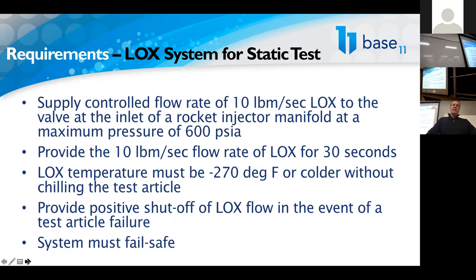And I think this would be true in all cases, whether it's a rocket or a static test, but we need the system to fail safe. If everything goes wrong, if something's not happening in the way you expect, you should have a simple, straightforward means of safing your system. And in our case here at Purdue, like we talked about on the tour, we fail safe by killing power. If you kill power, everything goes to a safe condition because no power is a very achievable state.